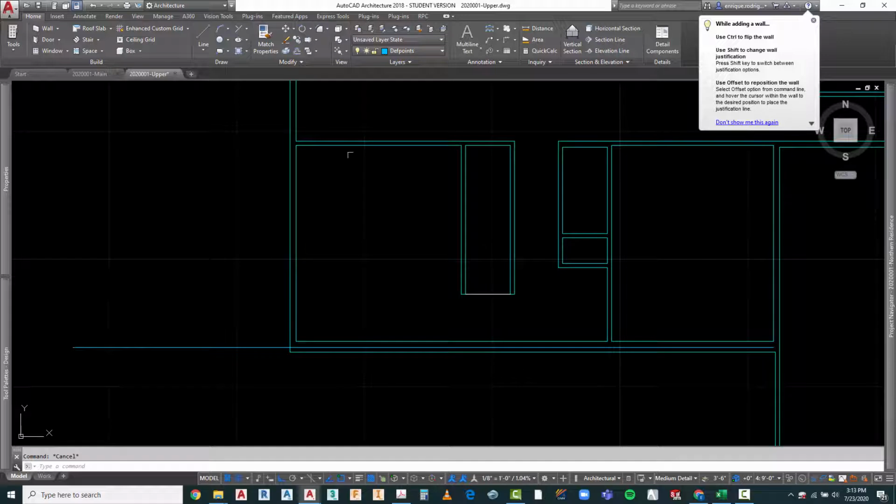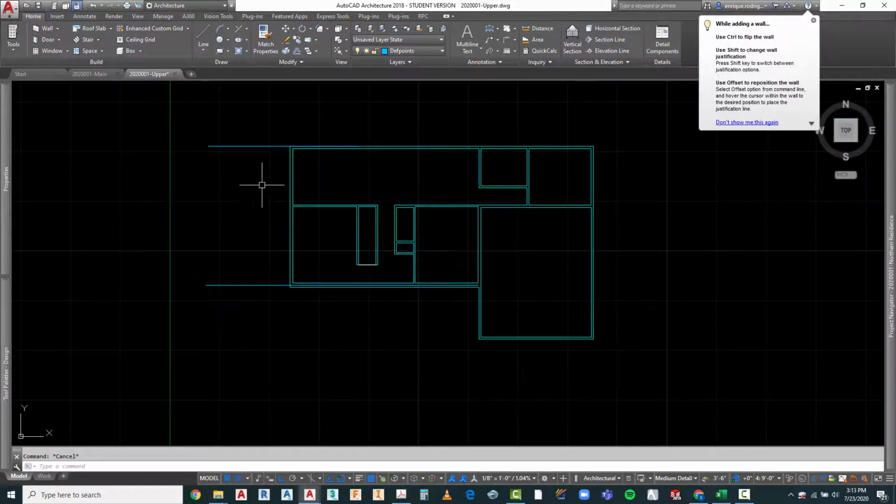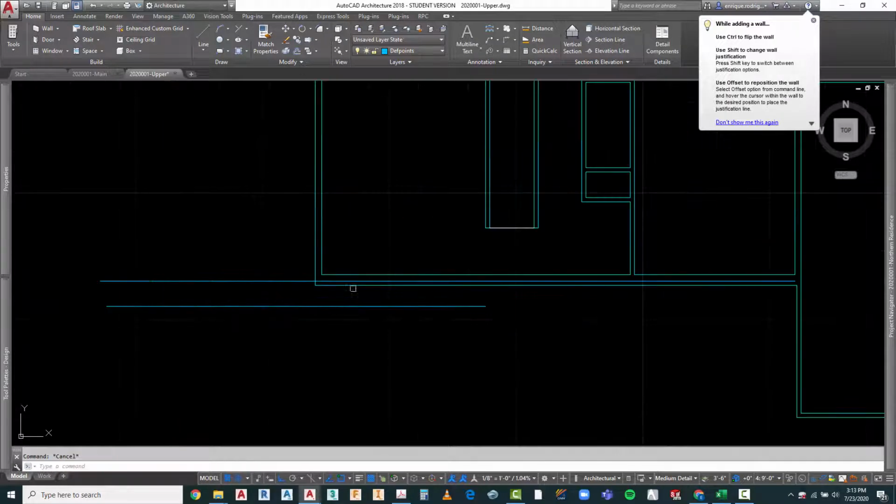And the reason I need that is because of the way that this sets things up, I want to make sure to double check it. So I'm going to go ahead and draw this line in here. The markups tell me that this is going to be 30 feet down here. So this should be a 2-foot offset. I'm going to do a right in there, and I've got my 2 feet.